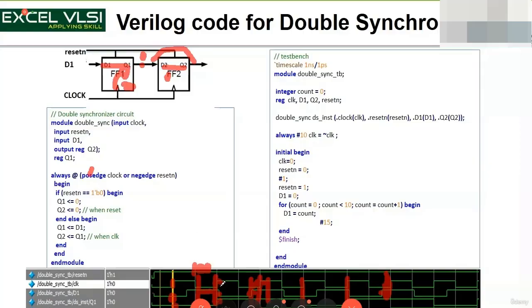Now with respect to the rising edge, before it gives the output, that is Q1, it will be coming after this delay, that is clock to Q delay. That is, if I say 2 nanosecond, you see the output Q1 from the edge of the clock, not from D, from the edge of the clock. That is why clock to Q delay. Okay, so it will be 2 nanosecond.